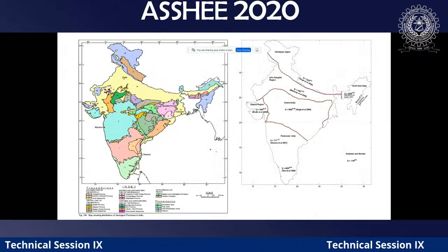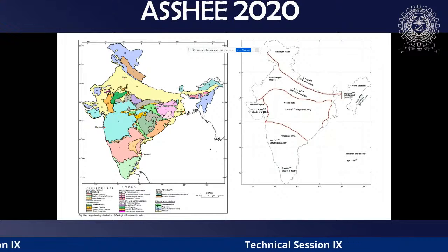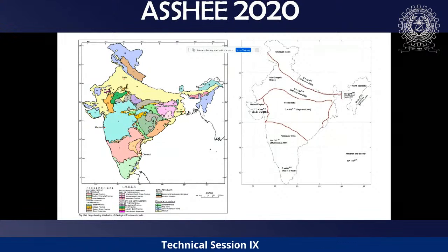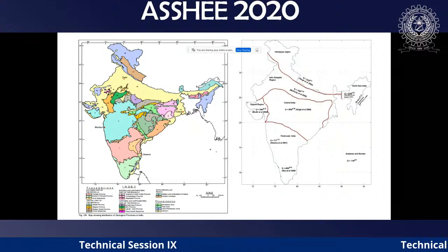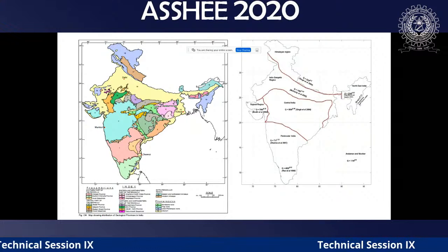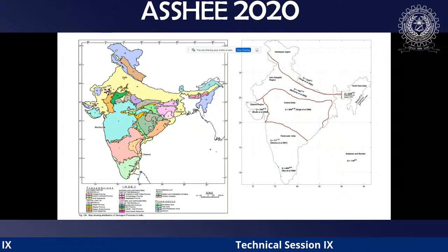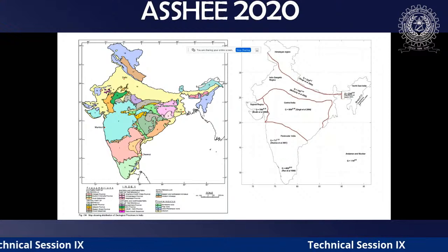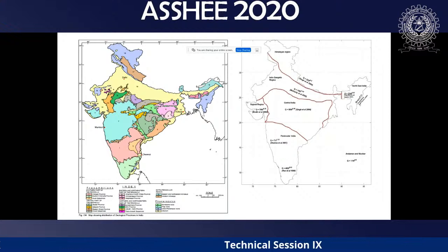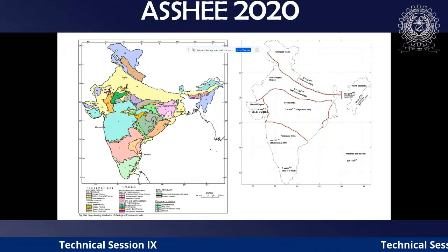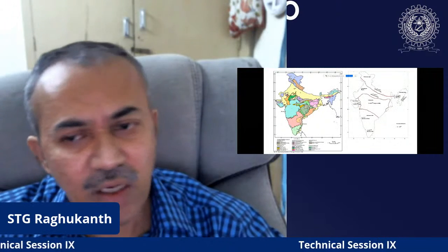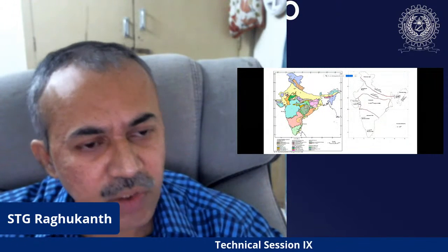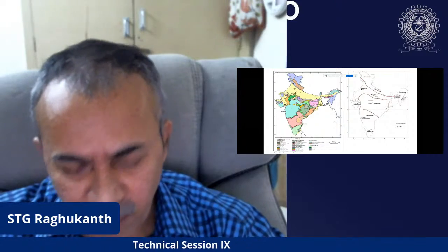Now when it comes to GMPEs, the whole of India is geologically very complex, with several things there. So we divided the country into three or four zones for estimating the GMPE relations. We have the Himalayas, then the Indo-Gangetic basin, then central India, then peninsular India, then the Kutch region, which behaves in a different fashion. Gujarat we have, then of course the northeast with the subduction zones, then the Andaman region. So we divided these into several groups for estimating our GMPE relations.